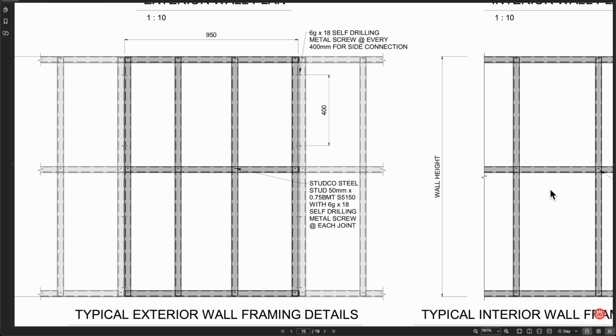If you're doing timber, that spacing's different again, and depending on whether it's a load-bearing wall, you're going to have 2 top plates and maybe 2 bottom plates. It depends on the application. Being a builder, you know when that's applicable. I have no idea. Also, when you're doing your timber, you're going to have these staggered as well. You might have more than just the one.